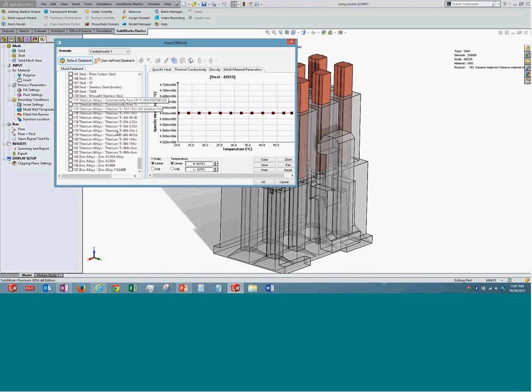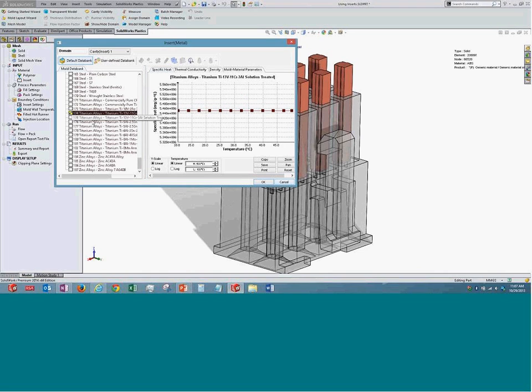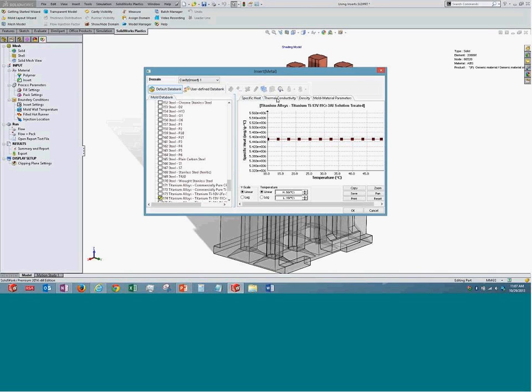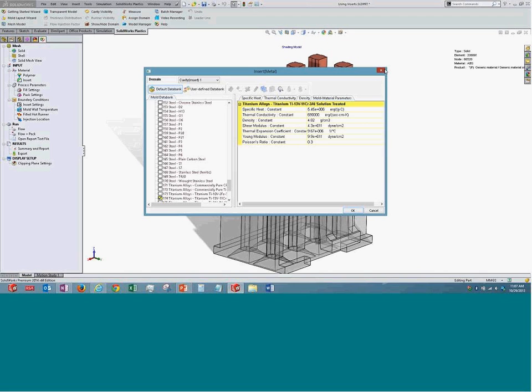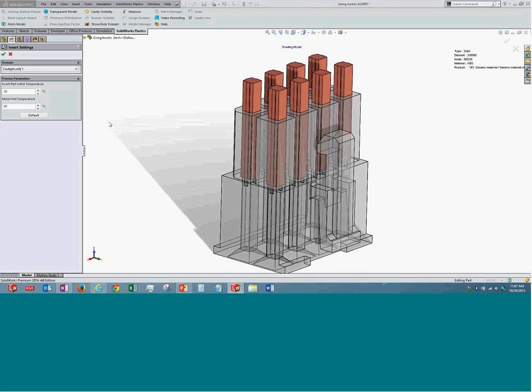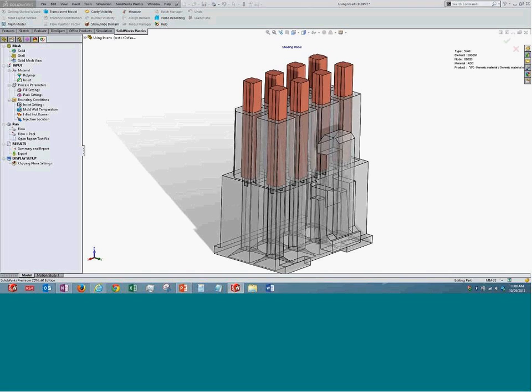Fill settings remain the same. If there are any insert settings, we can give them. This insert which is present can be maintained at a certain initial temperature. So we can give it its initial temperature, a particular value that we decide when the filling starts. Mold temperature remains the same. Injection location we discussed. So in terms of the different steps that we are doing, it is almost the same, except these few different things which I showed you here. I will jump on to the results over here.